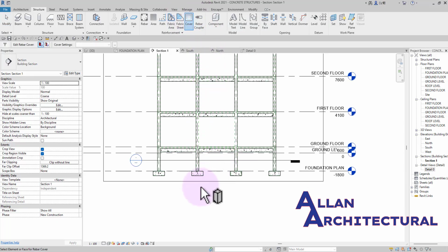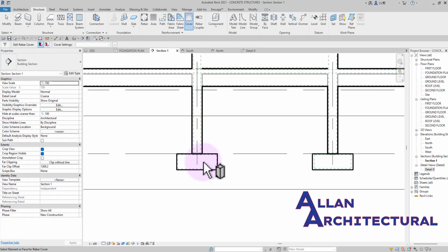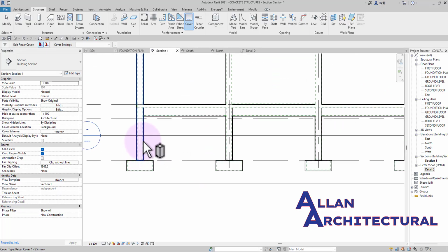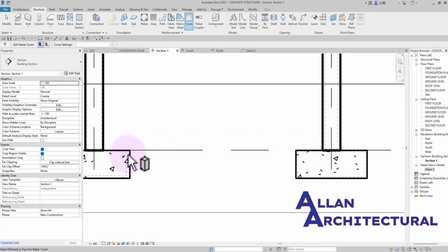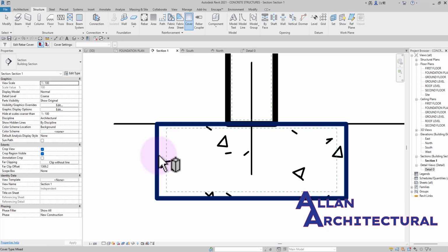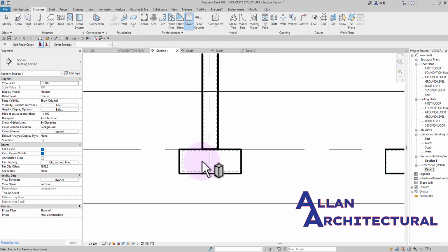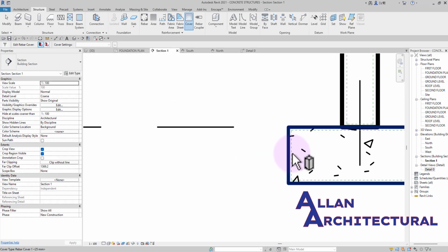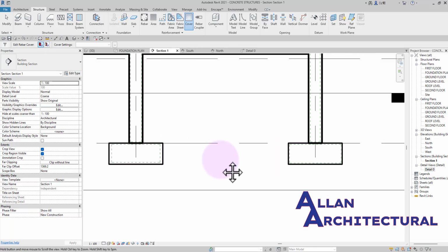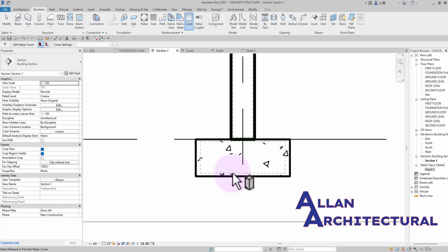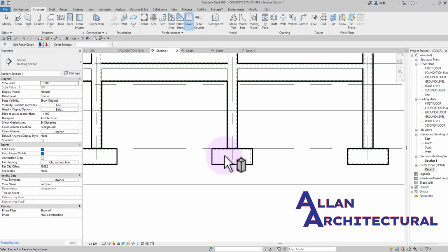You can come in here, to the rebar cover, and you're going to notice all of these green hyphenated lines. They are more inside, the green line has gone inside, unlike here, where I haven't changed the rebar cover. That is set to 25 millimeters. It means that our rebars are going to stay within the confines of this rebar cover. All right, so that was just by the way.